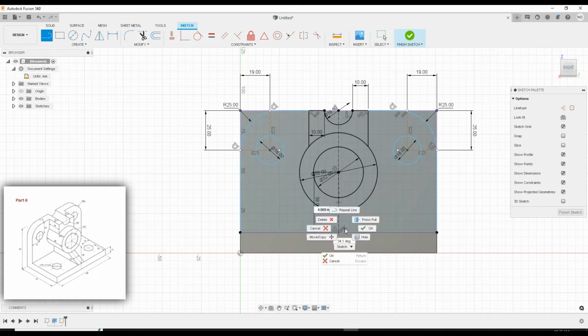So you want to go to this midpoint here, go over, and it's going to be 7.5. And then we're going to do the same thing over here off the midpoint. Okay. And now with those same line segments, you want to carry from this point up until it hits the intersection. It's going to snap to it. Same thing. All right. So now we have that in place. It's going to make our lives easier. It's going to make everything easier once we start extruding stuff.